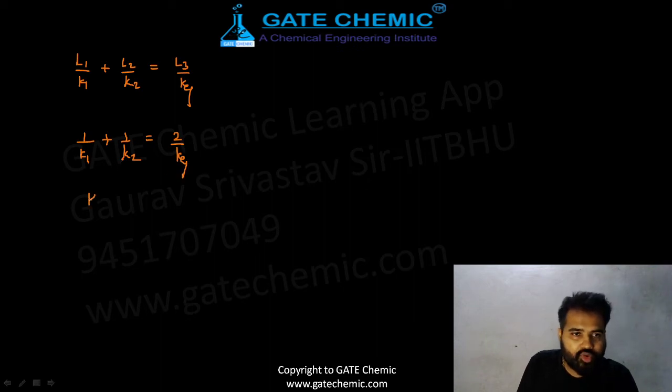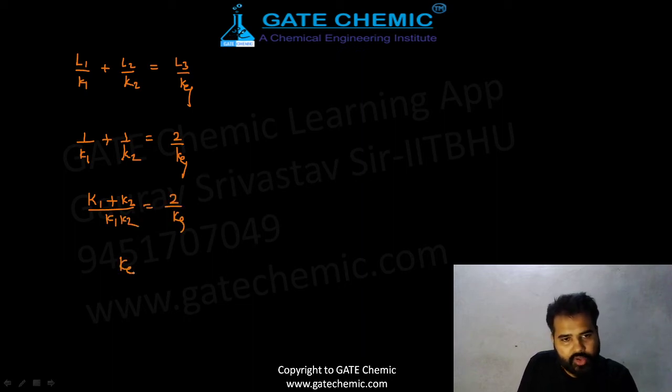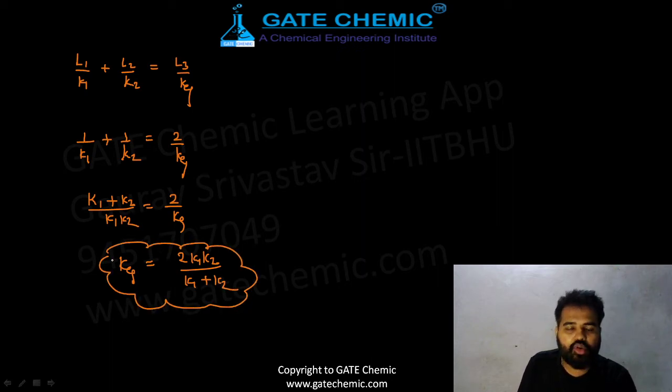After taking LCM you can write K1 plus K2 by K1 K2 equals 2 by K equivalent. So K equivalent can be written as 2 K1 K2 upon K1 plus K2. He could ask only this equation too, beta. Okay beta, everyone crystal clear? Shall we move forward to my next beautiful problem?